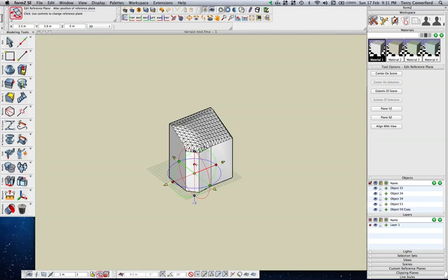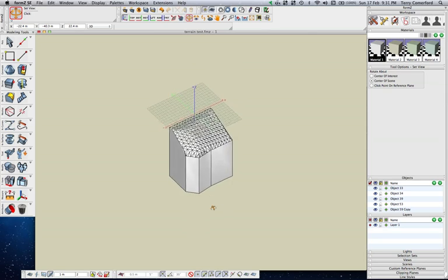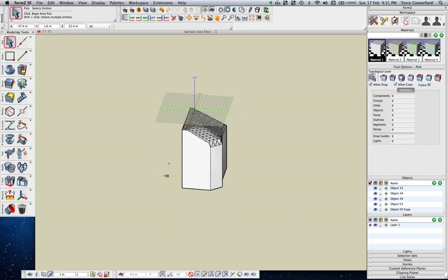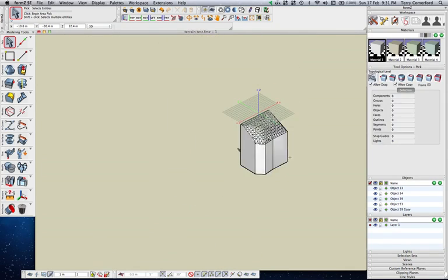If I click on the vertical blue line and then move that whole thing straight up the page till it's a reference plane that's on top of my site, and click up there, and then click Pick and Pick Out, I've now established a reference plane which is above my topography. So I'm going to be able to draw a little bit better onto it.